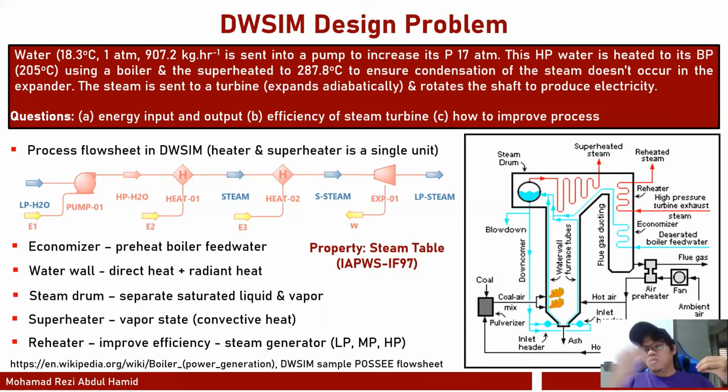So as opposed to going to the medium pressure turbine system, instead of using that slightly lower temperature steam, they send it back to this boiler to reheat the steam before it enters the turbine again. So basically this is just to extract as much heat as possible and to make sure that the efficiency is always high. Because if you learn thermal, you know that based on the Carnot cycle, right?